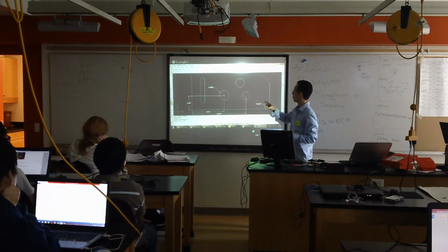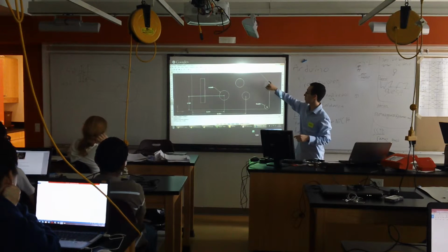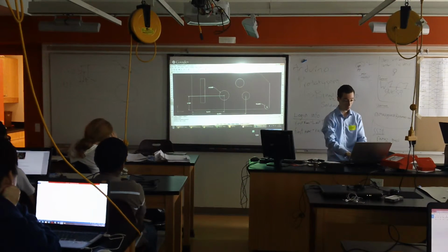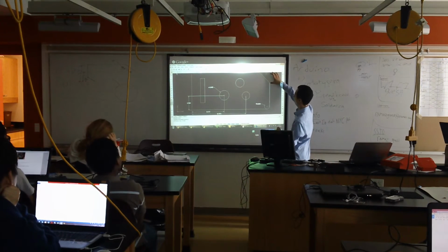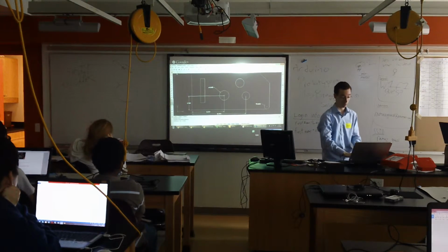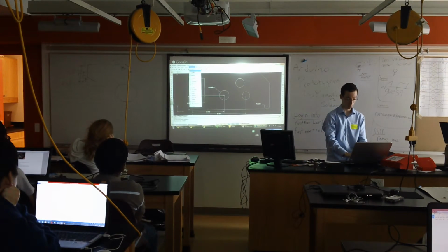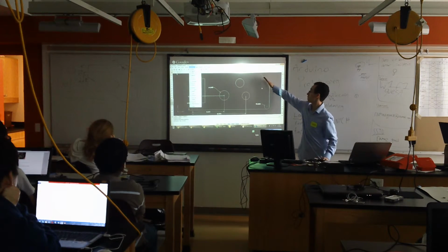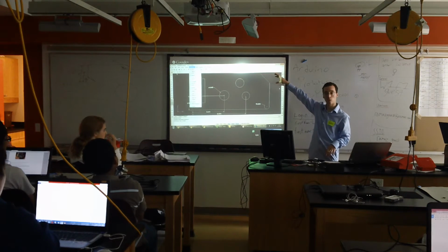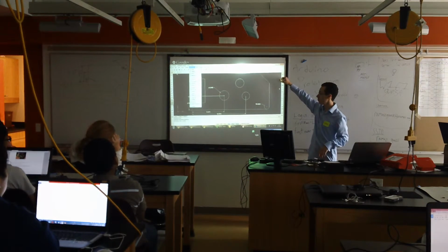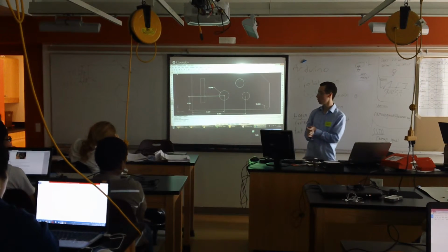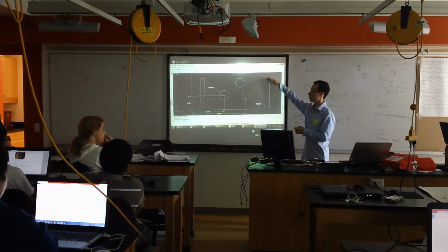Good, okay, great. The only other thing I'll say is that for this kind of chamfer here, you can dimension it two different ways. One is to dimension just how far this distance is, and how far this distance is. Another way that can sometimes look cleaner is to dimension an angle. So I could dimension this angle here and then give the distance, and that might look a little neater sometimes. That's really everything that you'll need to know: how to put in holes, slots, linear dimensions, angles.